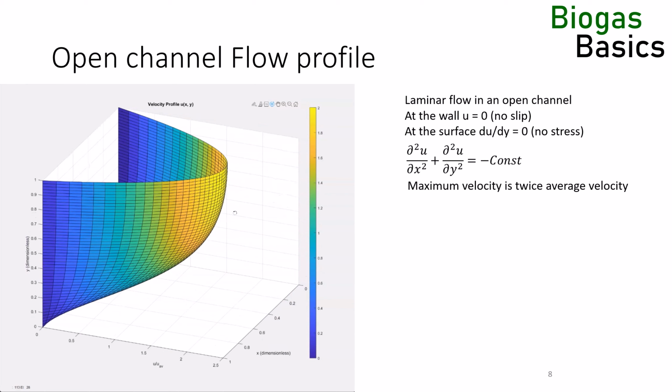Unlike the turbulent plug flow, the Bingham-plastic flow is not characterized by perfect radial mixing. In fact, the core has no radial mixing at all as it is solid. Between the edge of the core and the wall, the shear is high enough to fluidize the medium. It effectively acts as a lubricant. I will talk more about Bingham fluids and where they appear in AD in the mixing and rheology presentation.